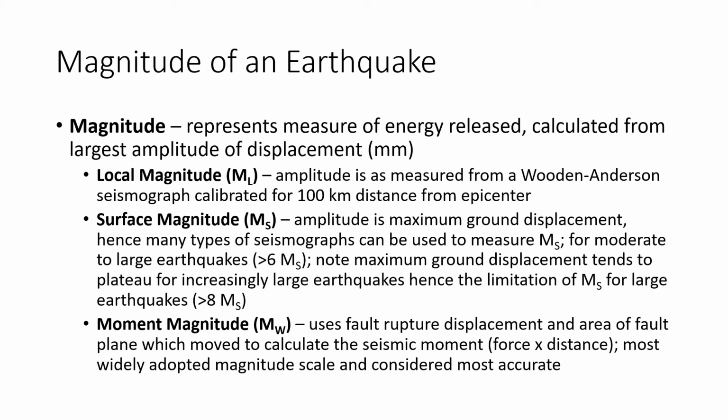Although the limitation of your surface magnitude is, when you have a large earthquake like magnitude 8, after magnitude 8, like magnitude 8.1, 8.5, magnitude 9, so beyond magnitude 8 earthquakes, the relationship between the size of the earthquake and the maximum ground displacement becomes non-proportional.